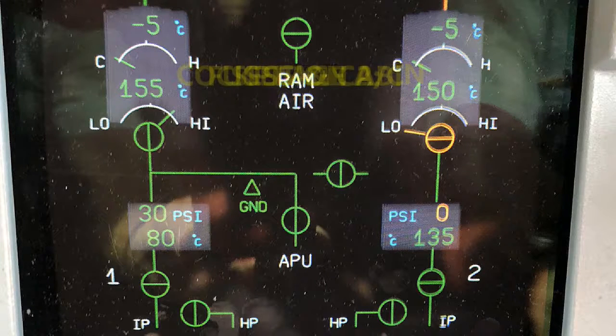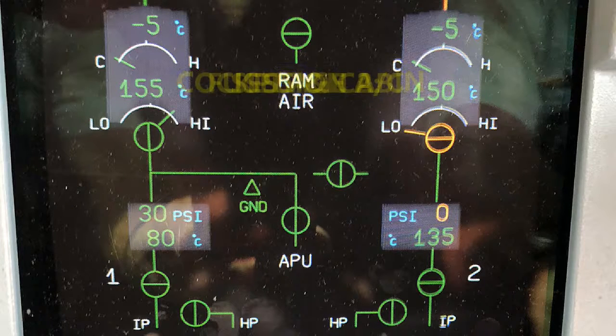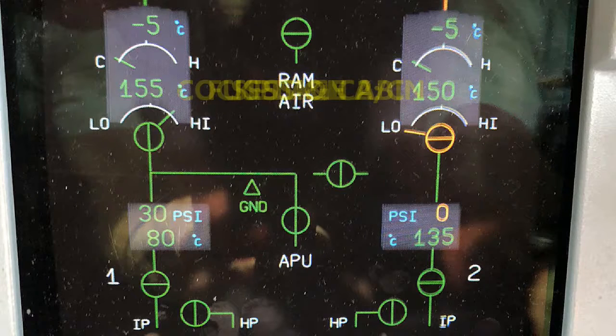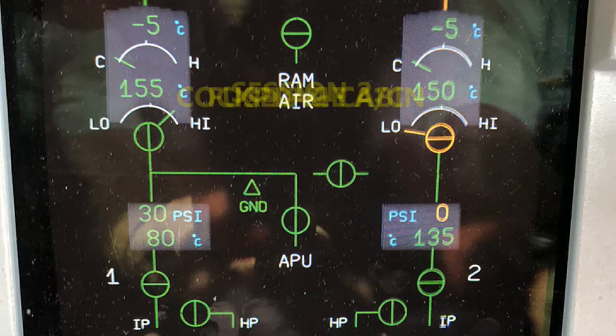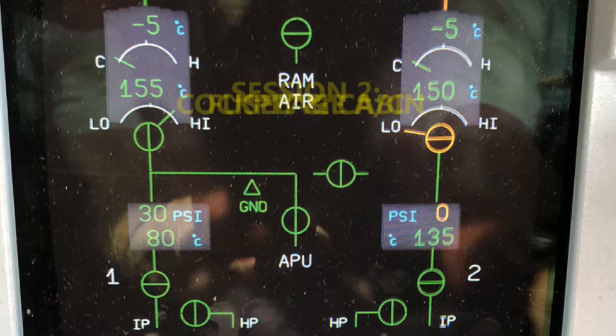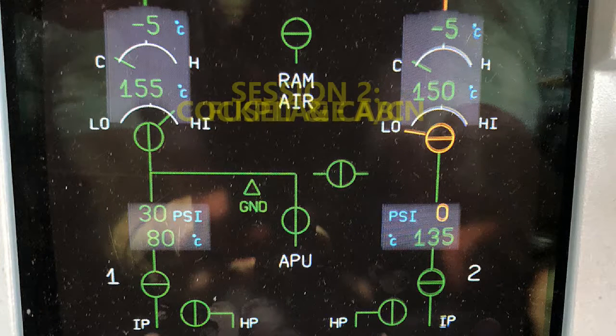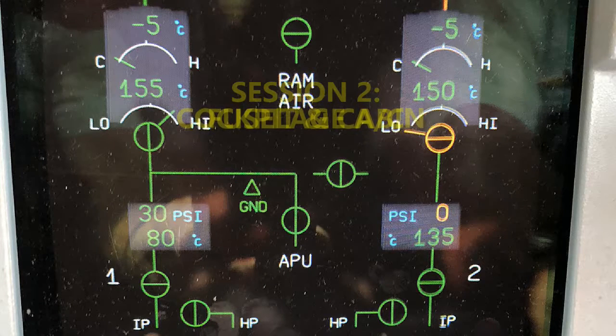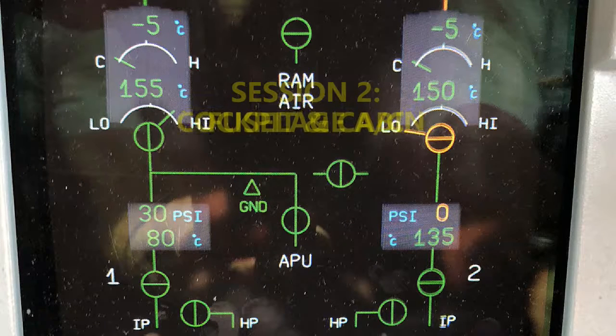So with the cabin pressurization, we have, of course, controllers again. These are the computers. There are 2 cabin pressure controllers. They are located in the avionics compartment and are on shelves 95 VU and 96 VU on the main rack 90. So those are those 2 that are going to be controlling pressurization and monitoring. Just some of the functions that are involved with these controllers.